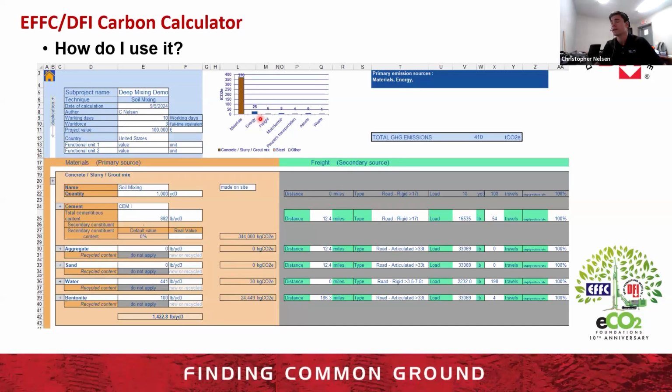Now, this is because based on those case studies, we found that in general, per unit volume of material used, deep mixing will use more fuel or energy usage in general than jet grouting. That may not still be the case. It may not be the case for your specific project, but it really helps early on in the design and project development phase, kind of tailoring your expectations.